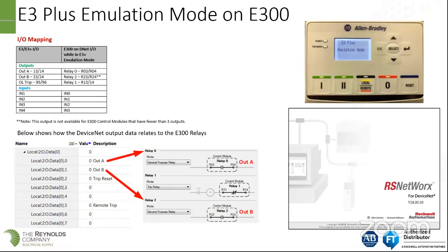This allows a user to reuse configuration parameters from the E3 Plus when using configuration tools like automatic device recovery, which is ADR acronym, the DeviceNet configuration terminal, which is a separate part you can buy, and that part number would be 193-DNCT, and then through RSNetWorx for DeviceNet. So next slide, Dave.